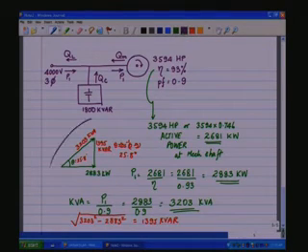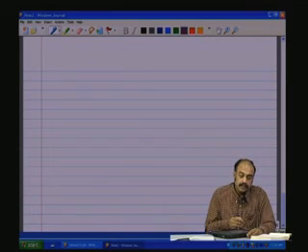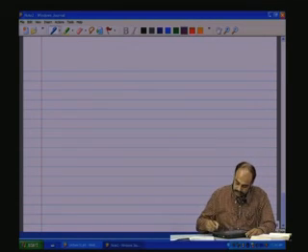So, this would be our power triangle. As far as this portion, that is the load portion, is concerned, this is without having considered the capacitance reactive circuit that we have put in there. Now, if the capacitance circuit is put, which is 1800 kVAR rated, that capacitance is going to generate QC.